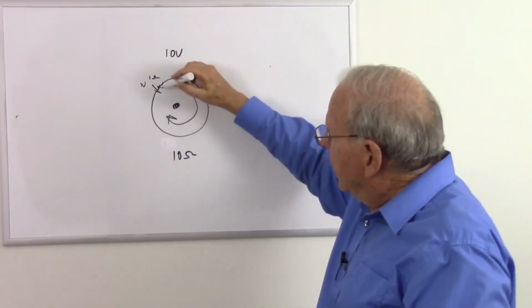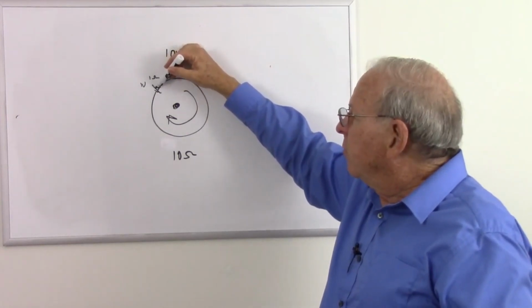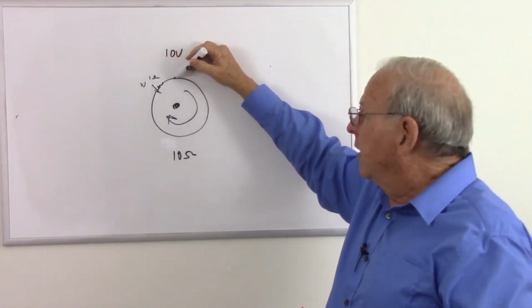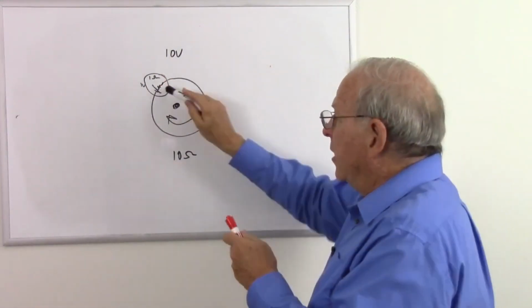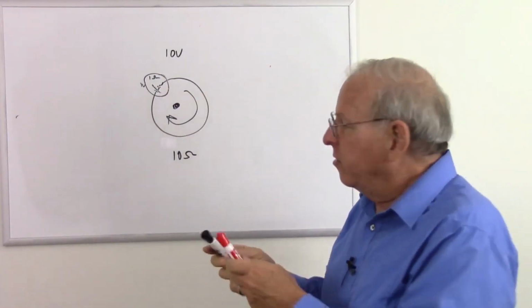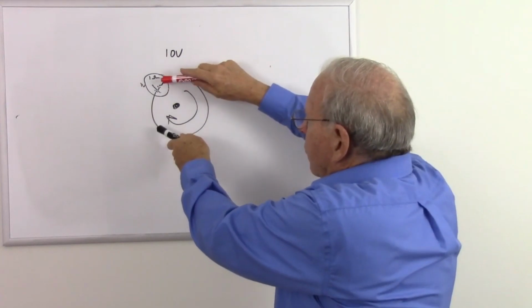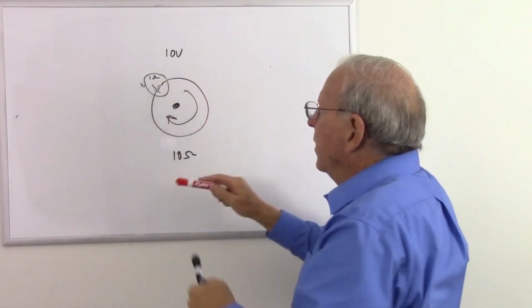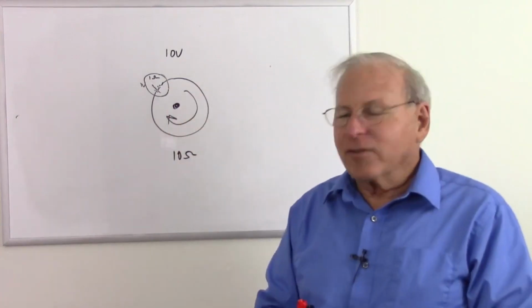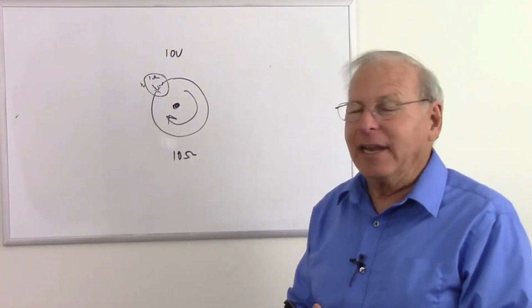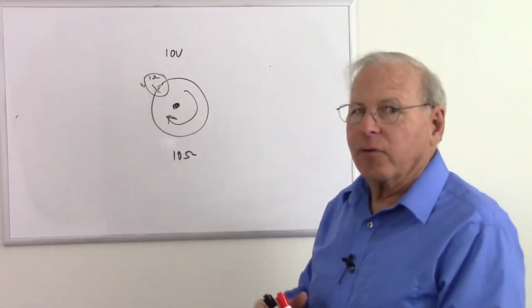As the current flows through, we gain a volt from here to here, negative to positive, but then we lose a volt, positive to negative, going there, and we do that every place around the circuit. So each of these entities is self-contained. We cannot probe in between the battery and the resistance. So I can only probe between the whole entities. So no matter where I put my meter, gain a volt, lose a volt, I always have 0 volts no matter where I look on the loop. So that is how voltage acts in a loop when we have uniform voltage and uniform resistance throughout the loop.